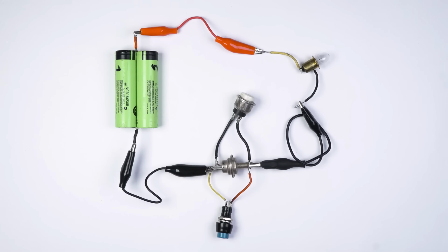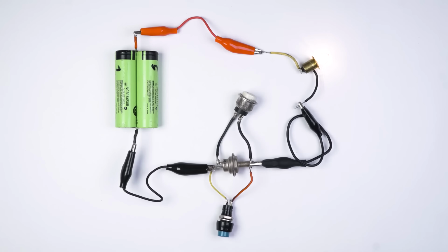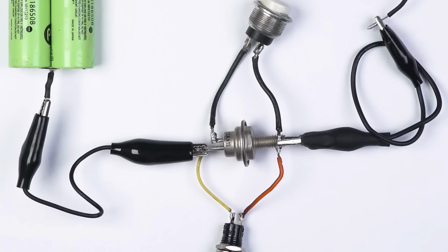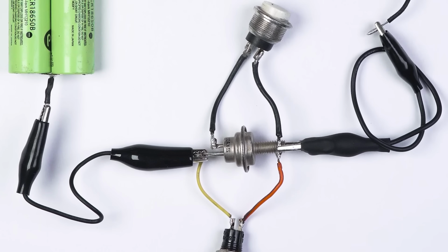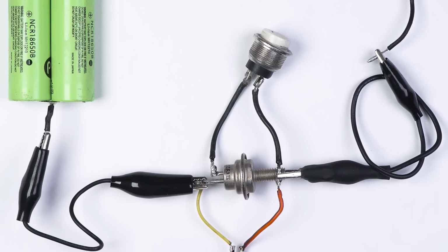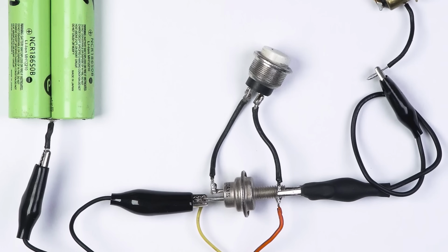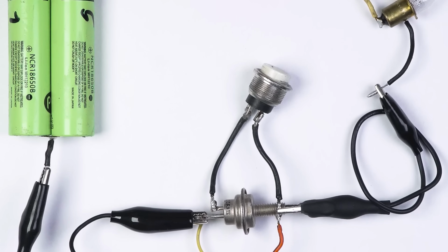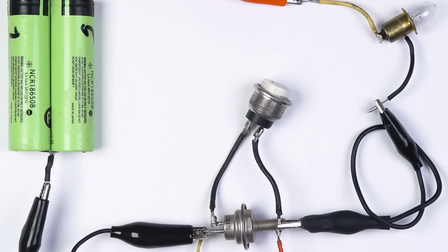Oddly enough, this is basically about all the THYRISTOR is capable of, that is, to work as a latch switch. In reality, latching is more of a disadvantage, because to turn the SCR off, you always need to utilize an additional circuit. Because of that feature, THYRISTORs are mostly used in AC circuits, where the oscillating sine wave, twice in a period, cuts off power to the THYRISTOR and resets it to the original state.